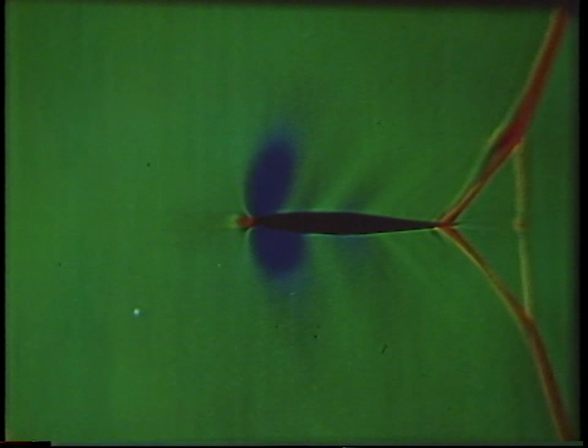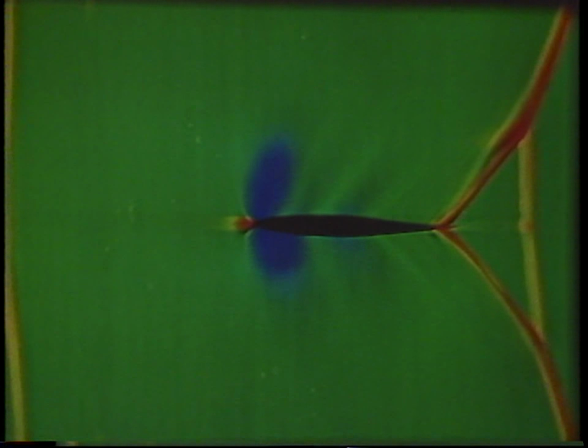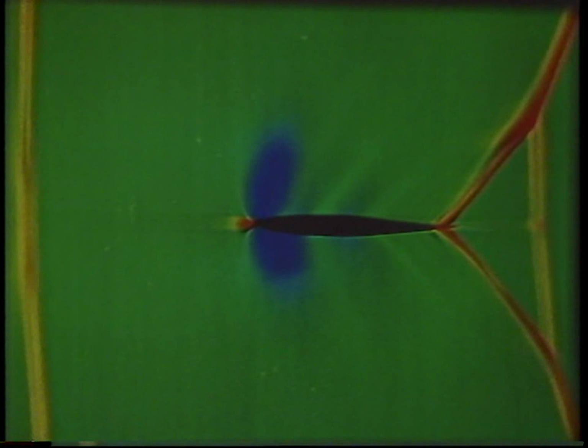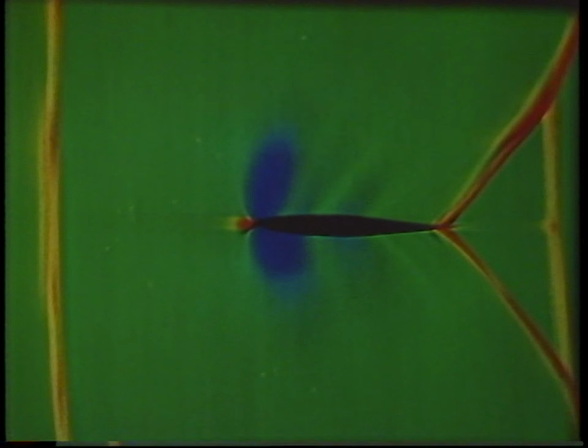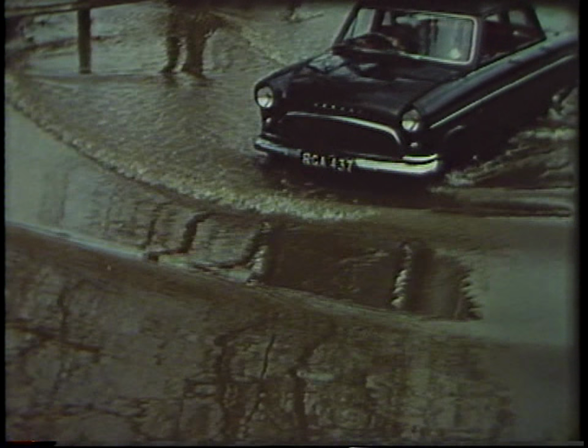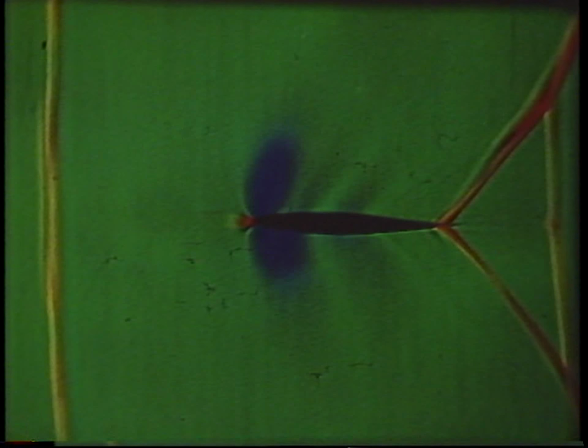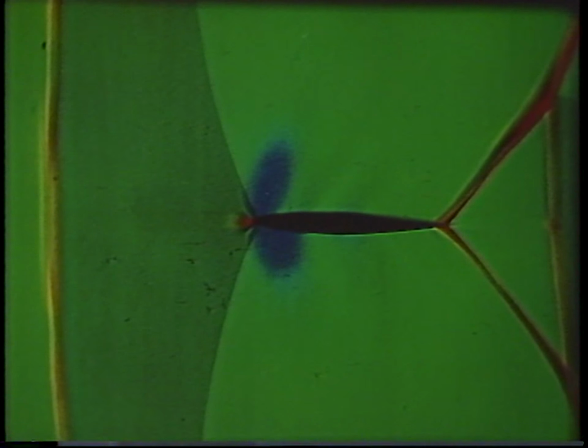The flight Mach number has just passed Mach 1. The free air stream is supersonic now, and another shock wave appears in front of the wing, the bow wave. It's something like a bow wave on the surface of water. As before, the supersonic regions are lighter green. Like the shock waves on the wing, the bow wave is formed by the constant piling up of pressure waves, this time from points near the leading edge inside the subsonic region.